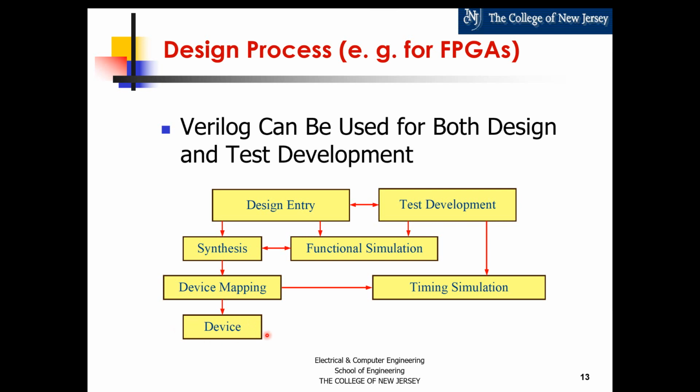Again, if you're doing an FPGA, this is just downloading what is called a bit file to the FPGA, which basically tells the FPGA how to route the signals to get the hardware functionality that you meant to design here. But if you were doing a full custom chip, this step really is huge, right? You have to generate masks, you have to do geometric verification, you have to do layout versus schematic checks, and all kinds of things. You have to do reliability checks for things like electromigration and things like that.